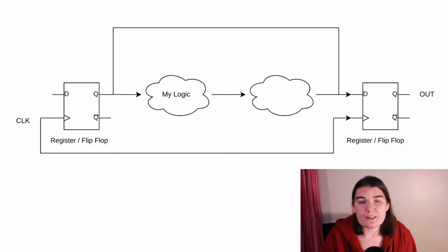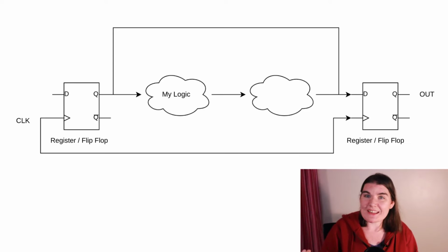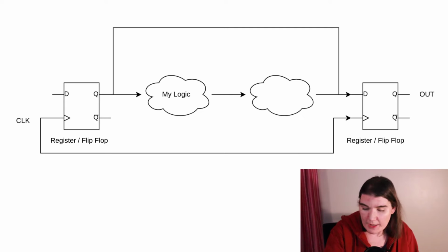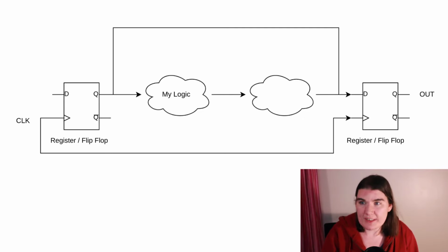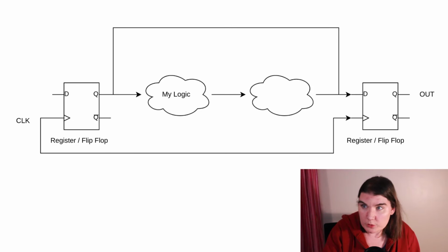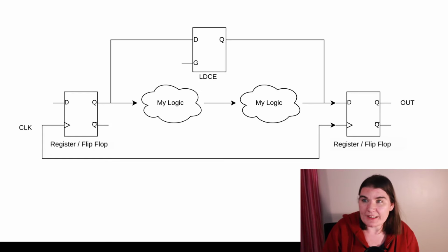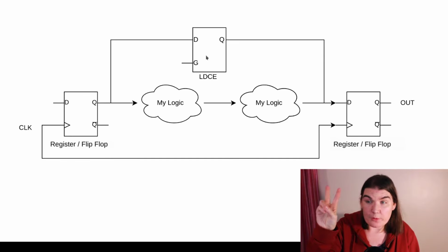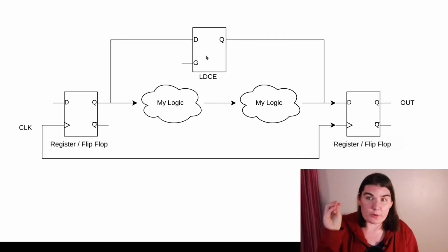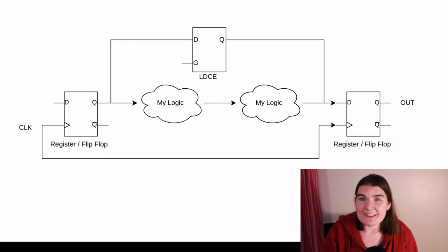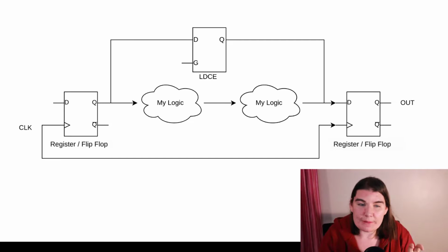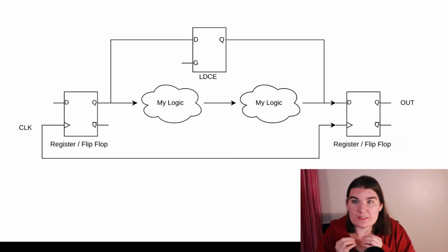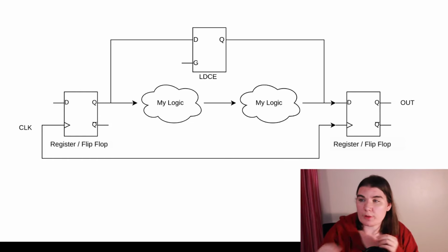And so as a result of that, this tool is not able to properly perform static timing analysis on this path. And because it's not able to, in order to make an effort to stabilize the path, what the tool will do is put in its own fake memory element that's like a register. So this is a hacky memory element, and all its job is to stabilize the signal in the return path.